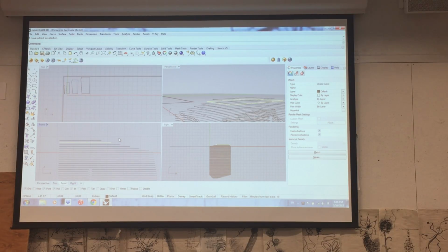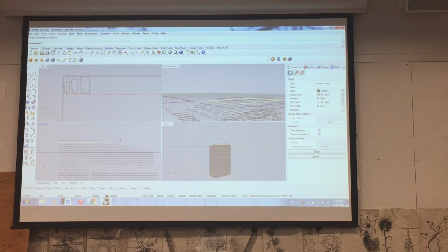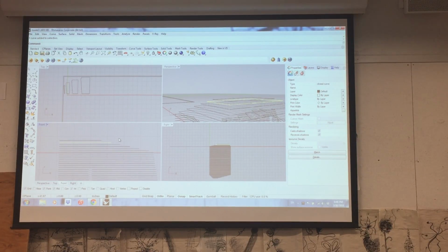And then you'll glue all of those sections together with super glue. Cyanoacrylate, MaxiCure. Not tacky glue, not Elmer's glue, not spray glue, not wood glue, only super glue. Don't paint them, don't sand them. When you're laser cutting them, keep track of what order they go in. If it laser cuts well, these pieces are going to fall out of your sheet, and you're going to miss layer 45 and 47 or whatever.